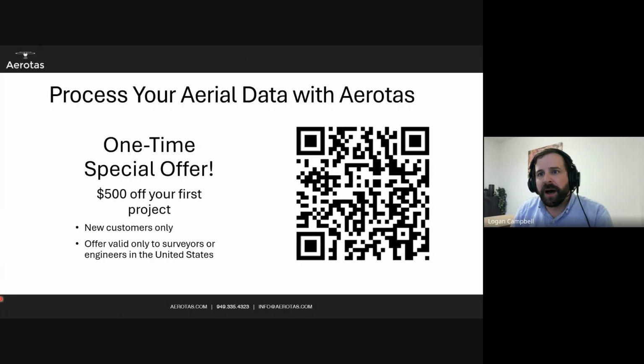Yep. We've got some good hardware recommendations around everything. Oh, is ground control necessary when combining photos with LiDAR? Strictly speaking, it is not necessary, but we strongly, strongly, strongly recommend using ground control with LiDAR data as well as with photogrammetry. While you can rely on no ground control, if your GPS processing is very, very good and tight, you can get away with no ground control.